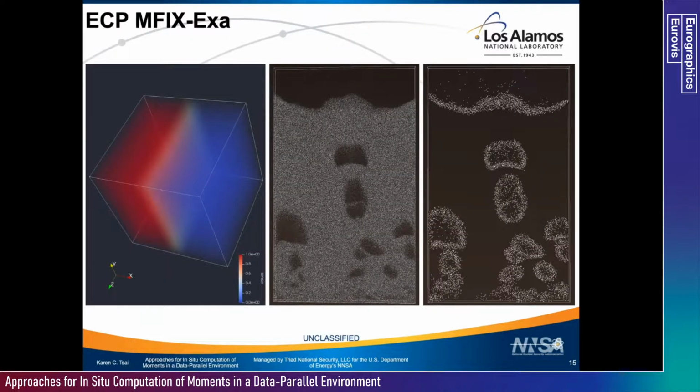Next is the ECP Infix Exa simulation. This is modeling the bubble bed using computational fluid dynamics discrete element model. Unlike the WarpX simulation though, Infix Exa does not have the Ascent or Catalyst integration already built in. So we build the simulation source code ourselves with VTK library directly linked in, and handle the conversion of raw data and all in-situ connection ourselves.